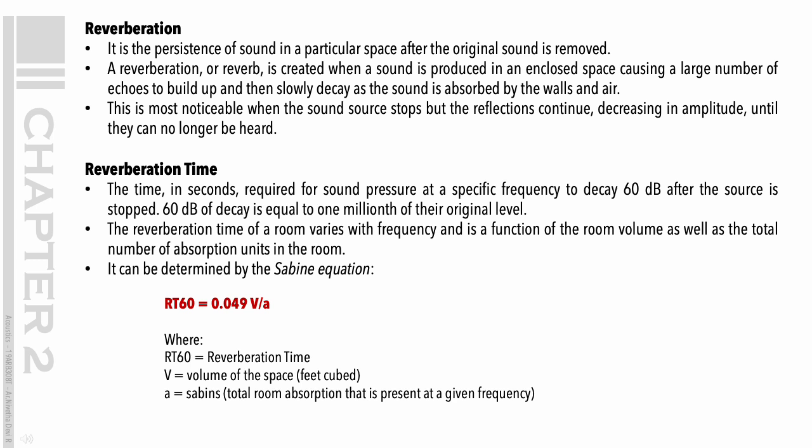The time, in seconds, required for sound pressure at a specific frequency to decay 60 decibels after the source is stopped. 60 decibels of decay is equal to 1/1,000,000th of the original level. The reverberation time of a room varies with frequency and is a function of the room volume as well as the total number of absorption units in the room.